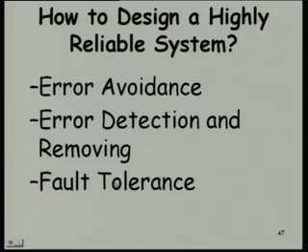No, fail safe is a state. Okay, let me just repeat his question. He says that the terms fail safe and fault tolerance appear to be confusing. That is the question. See, fail safe is when the system fails, but while failing it just fails in a state where damage will not occur. But in fault tolerance we are saying that even if there is a problem somewhere, we are masking it by some means, and how we are masking is through redundancy.